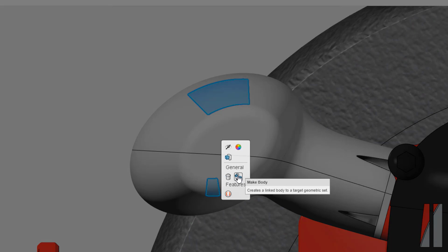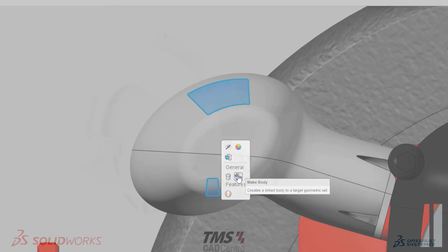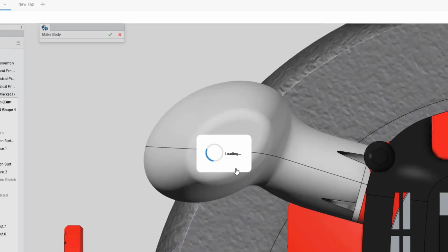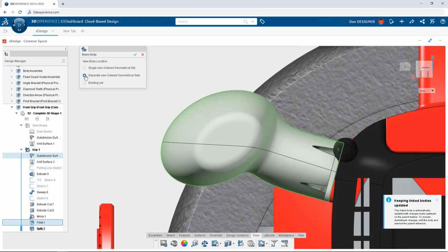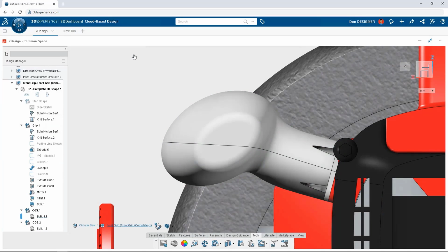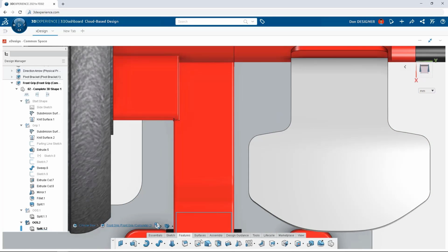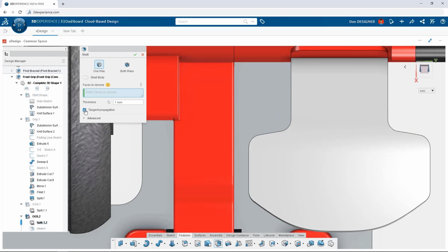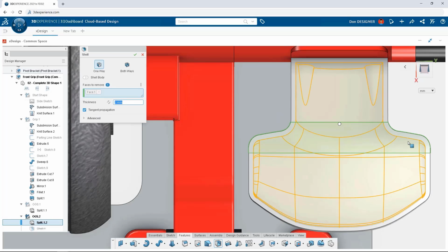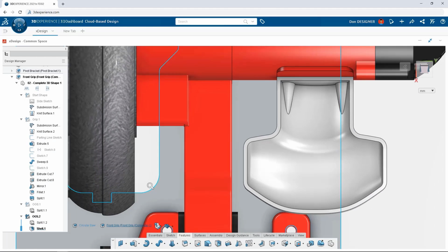From there, I'm then just going to select the face from the top and bottom sections, and this way we're going to look at something that we actually saw in the previous section with those geometric sets that we talked about. What we can do is basically select a face from each of the what would be separate components, and we can now separate those out to be new geometric sets. This now makes all the features completely independent from each other. That way we don't accidentally change one when we mean to change the other instead.